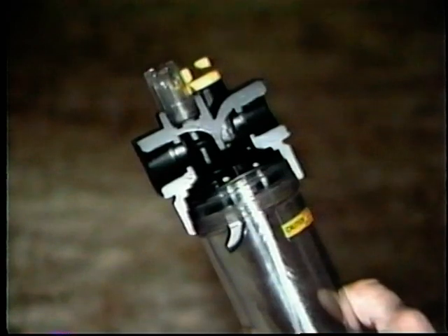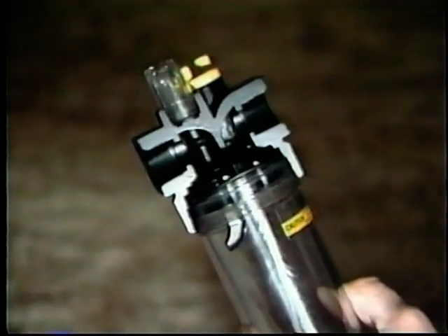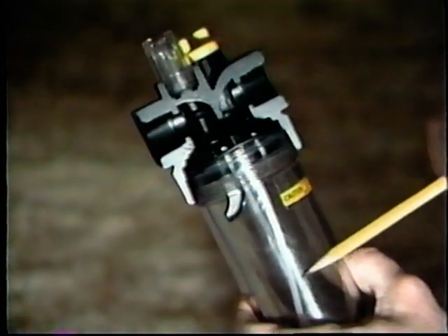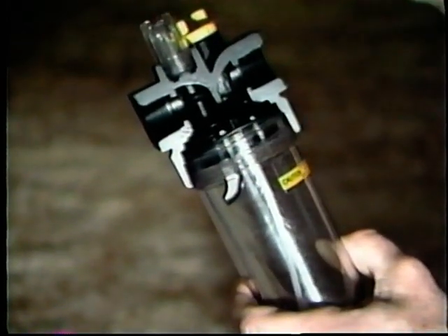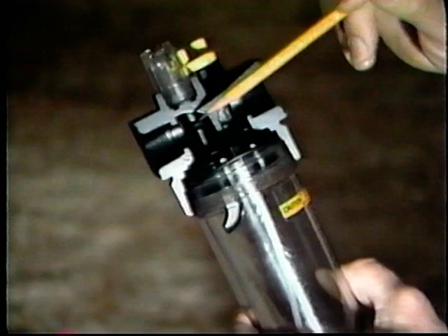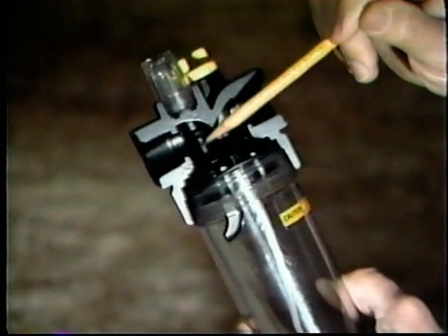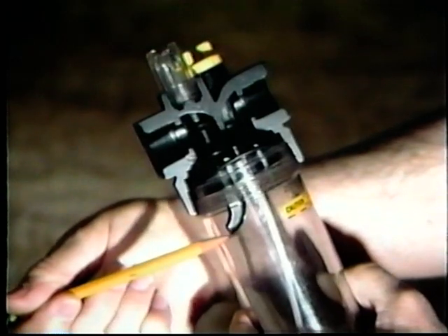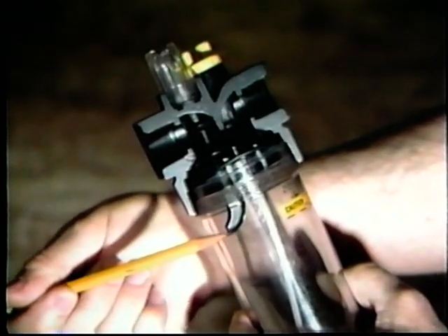The recirculating mist type works much the same as the standard mist lubricator. Venturi action draws oil up from the bowl and mists it into the downstream air. The difference occurs here, after the oil-air mixture leaves the venturi.